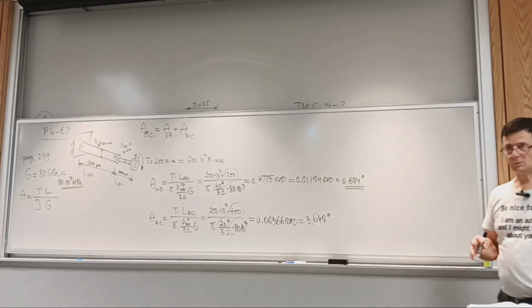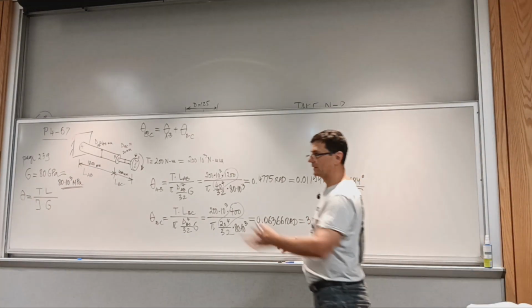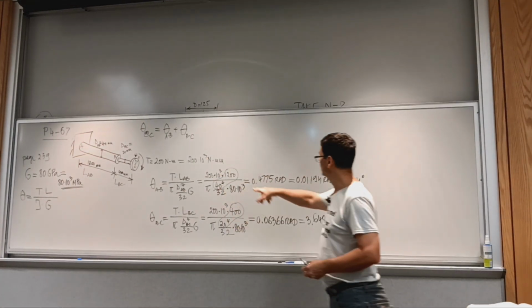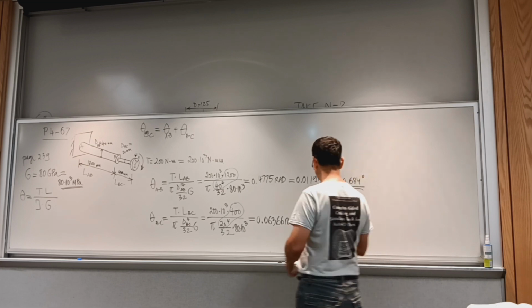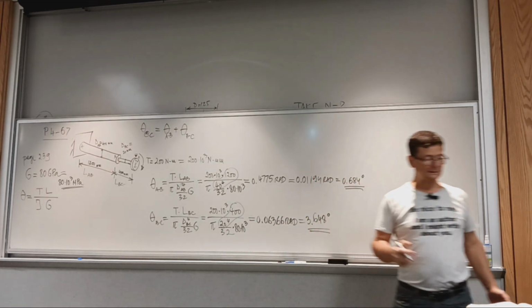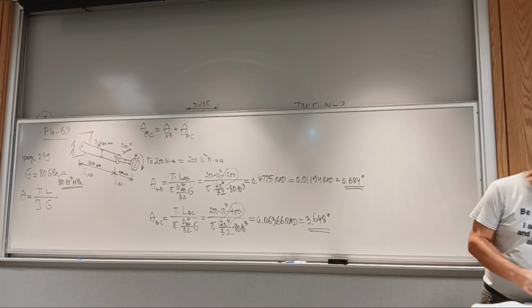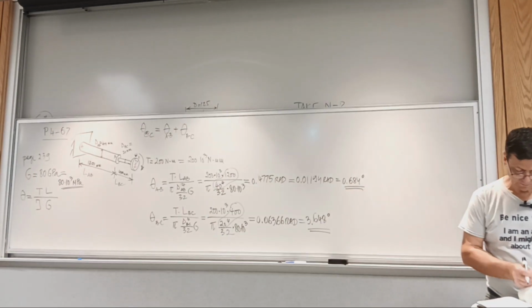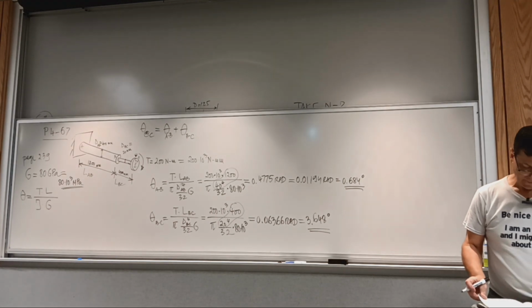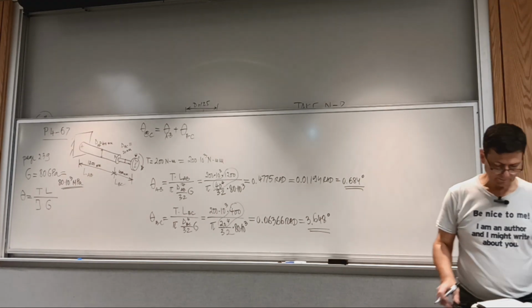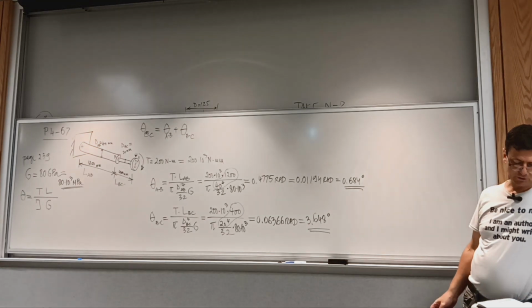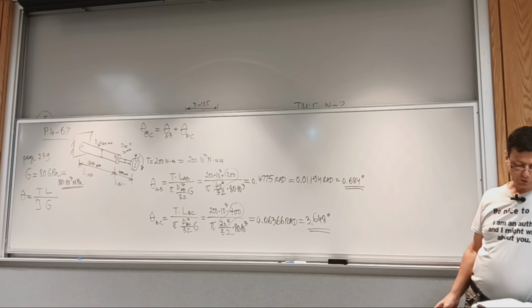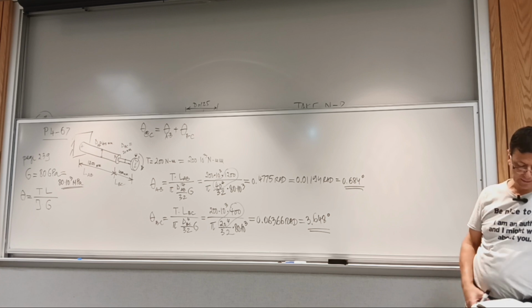It was a mistake here. I put power 3 instead of 4. We have some numbers, so we can analyze them from the perspective of what the book recommends. For torsional deformation, there's a recommendation for torsional stiffness. I'm on page 237, and it says recommended torsional stiffness is angle of twist per unit length.